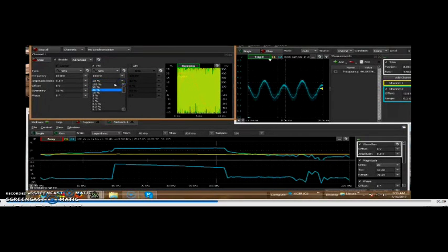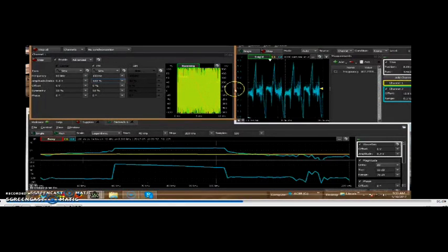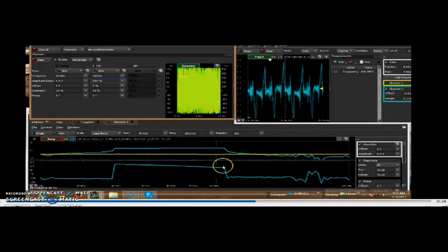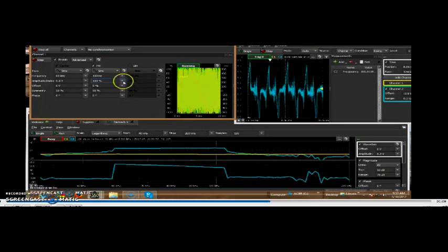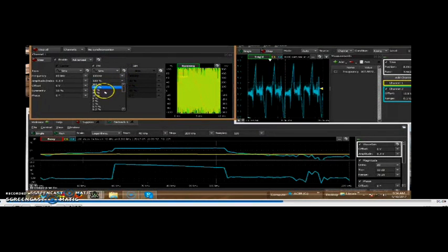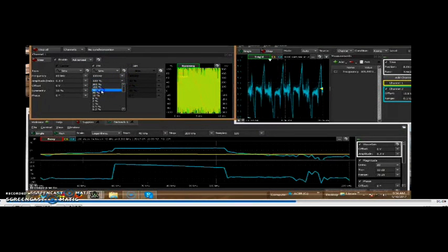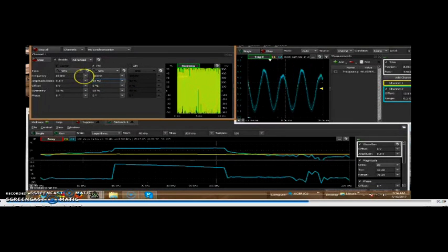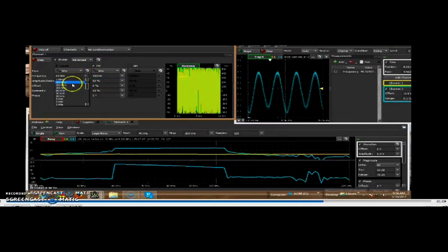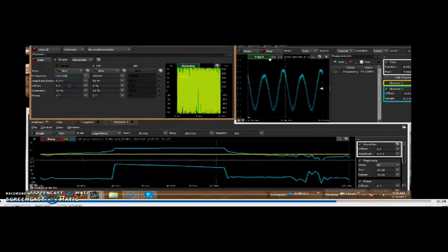The modulation index is increased such that the frequency swing goes outside the lock range. We are unable to get the demodulation. It can also be seen by changing the carrier frequency to a larger frequency, where the frequency swing goes outside the lock range of the PLL. We are unable to demodulate the waveform.